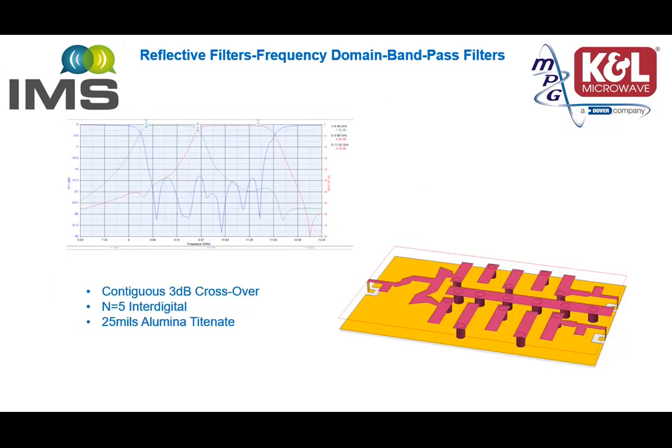The next example is for two bandpass filters, interdigital type with 5 resonators, that cross each other at exactly 3 dB. S11 from the common port is broadband match. This is a unique solution for wideband multiplexers. The realization is made on thin film alumina 25 mils with temperature compensation.